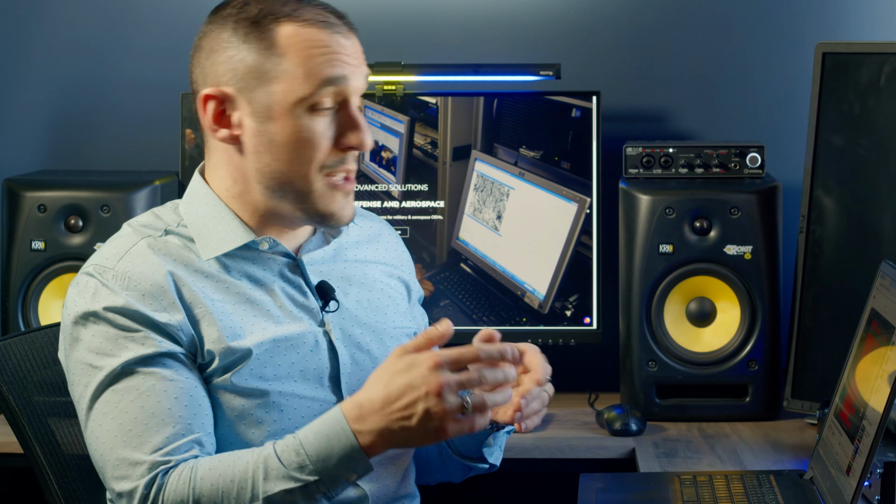Now, there are a number of reasons that this is a bad practice, and Super Jim mentioned one of them, which is it basically takes up all that space for routing. And you might say, well, of course, you could just delete one of the vias out of that footprint, right? Well, sure, you could, but you have to go back and make a copy of the footprint and then manually delete the via, reassign that footprint to that schematic symbol, and then update the PCB layout. And it's a big pain to do that every single time you need to eliminate a via from a footprint.